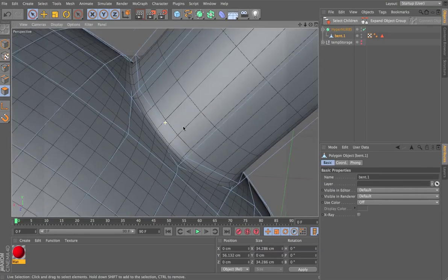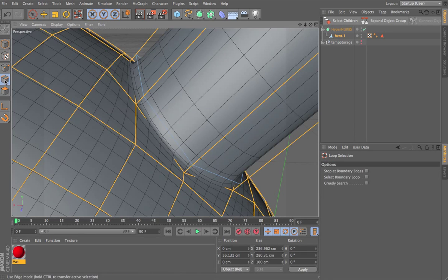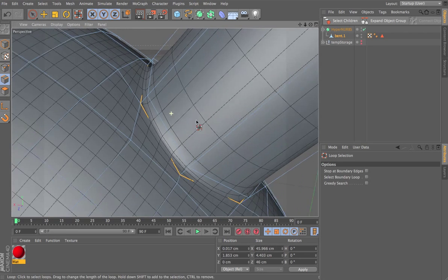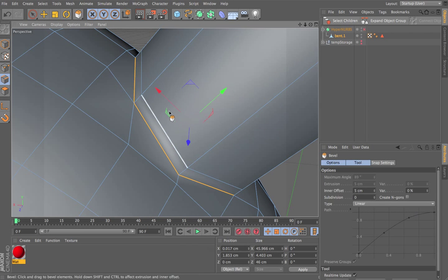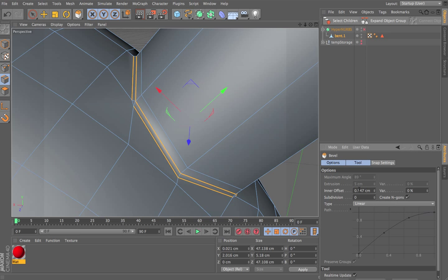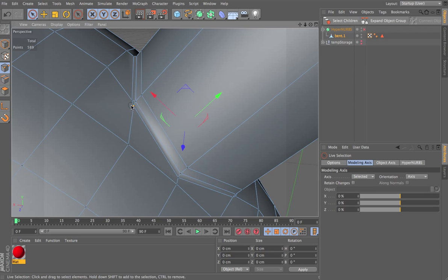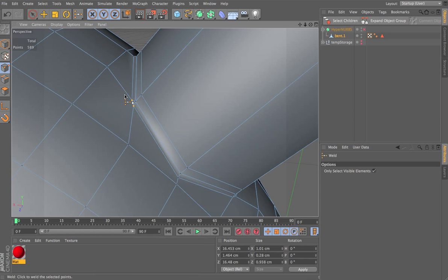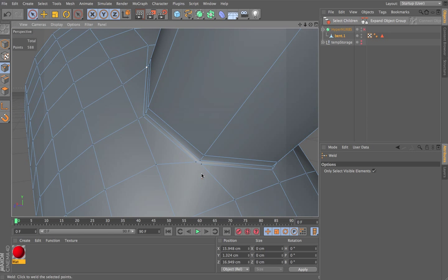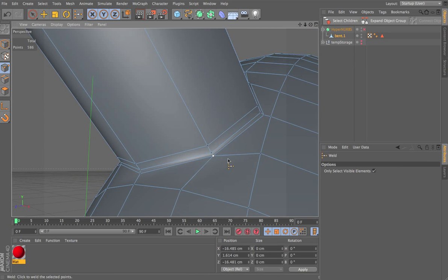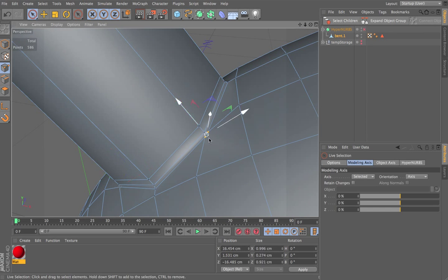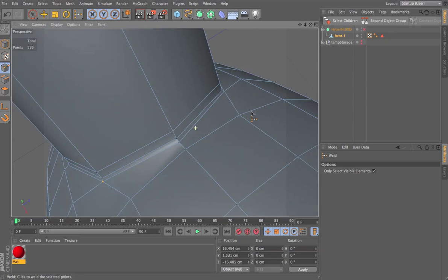Now the only thing we can't do automatically, what the gentleman did, is if we select this loop selection here, when the gentleman did a bevel, it was much cleaner. It didn't create these double edges. But you know something? Just keep your n-gons on, and then all you need to do is use points and just clean up these areas using the weld. These two, right click, weld, click there, come back here, space bar to go to previous tool, space bar to go to next tool, go around, space bar, click, move around, space bar, click, move around. Okay, he did it faster, good for him.